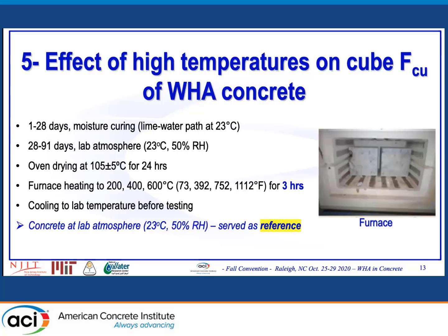So the heating regime which I followed is to put the specimens in a furnace and heat them for 3 hours at 3 different temperatures of 200, 400, and 600 Celsius. And after the 3 hours, I left all the specimens in the lab temperature to cool down before doing the compressive strength testing.